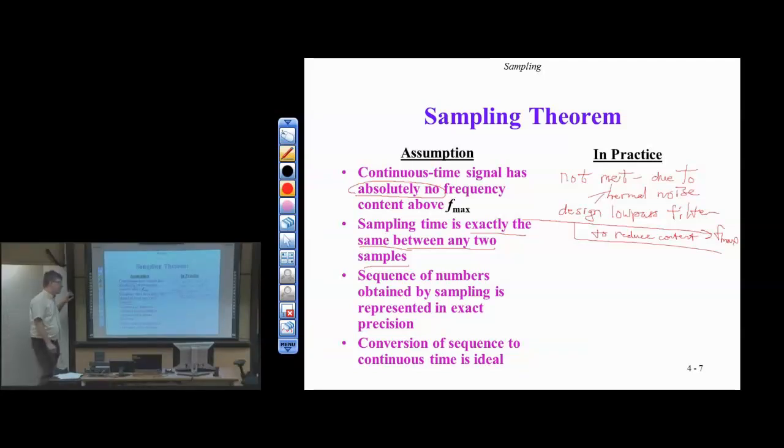So you have insight from just profiling the runtimes of software. There's always some error or jitter in the clocks. That's exactly right. So clocks are not perfect. They have a little bit of miss from one zero crossing to the next. The good news is that we can control this down to almost 1 part per million, certainly 10 parts per million with the right circuit design. So that's a relative error of 10 to the minus 5 or 10 to the minus 6. Just amazingly accurate.